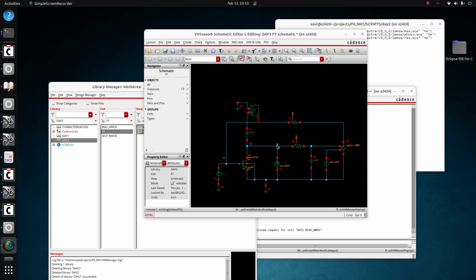At the drain of the transistor we are going to put a low pass filter, because what we are interested in amplifying is only the DC part. We are going to compare only the DC component of the drain voltage with the VDS that we have here at the right, and send the feedback back to the gate.